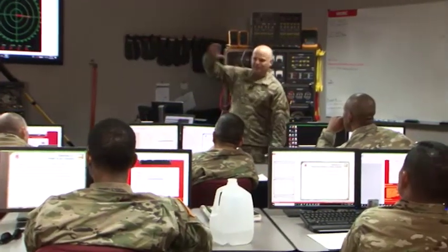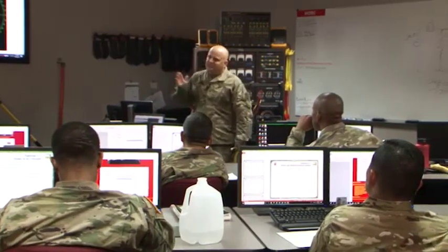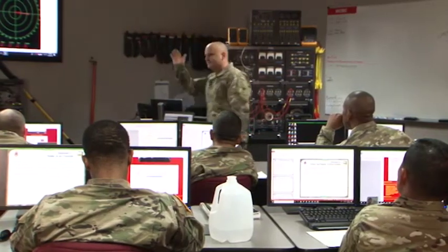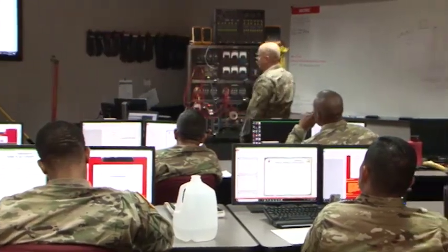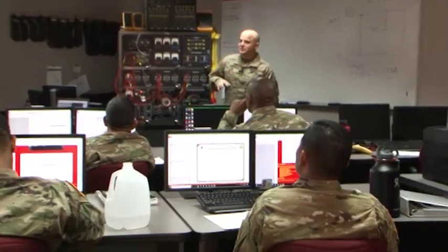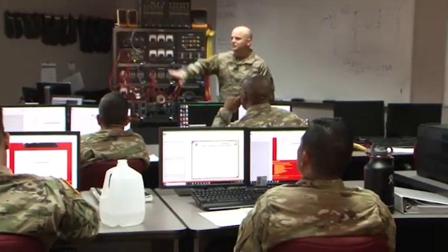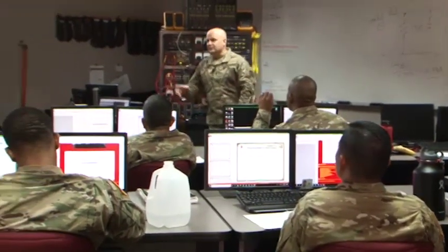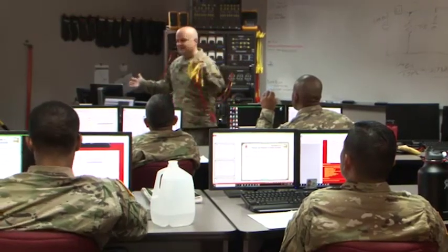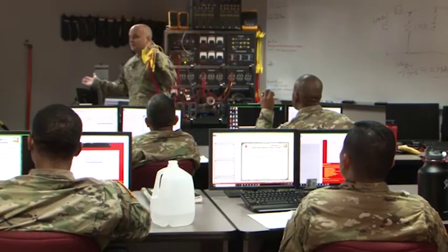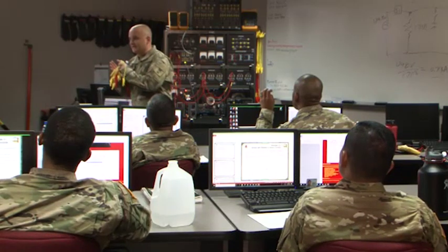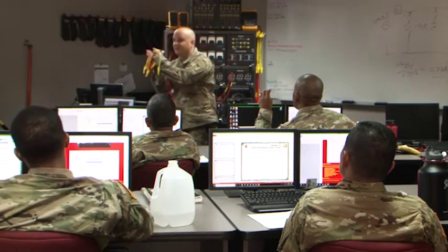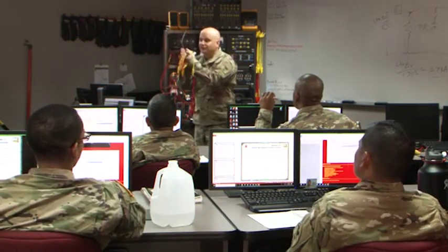All right, you're not getting that perfect 90-degree offset. You're getting a little bit off. So when you induce those same amount of values in there, that's why you're seeing that slight little variation right there. In an ideal inductor capacitor situation, when they say ideal, they're just negating all those little sciencey things like the resistance in the inductor, it would be perfectly 90. And then the theory would be that if you induce the same amount of capacitive reactance as inductive reactance, you're going to minimize the current vector, right? It's going to decrease, and it's going to come back to what we call unity, where there should be 0 phase angle between current and voltage, and that would be a perfect scenario.